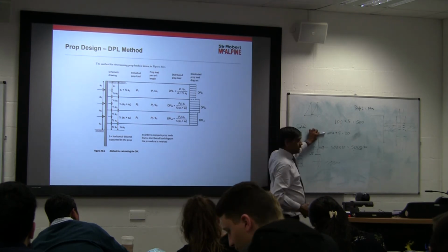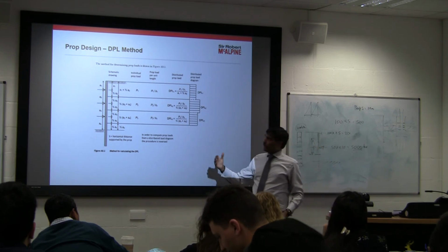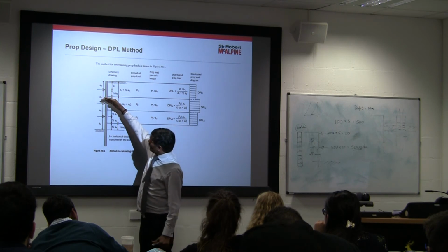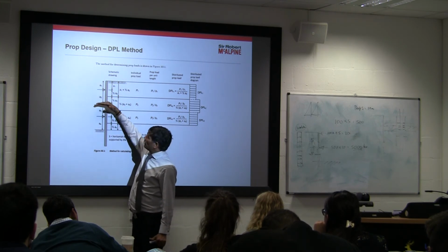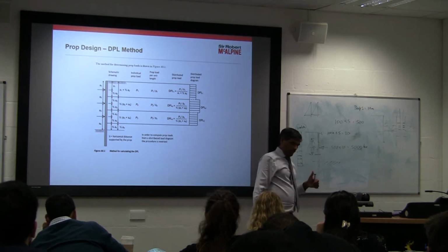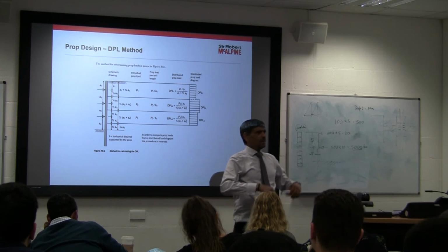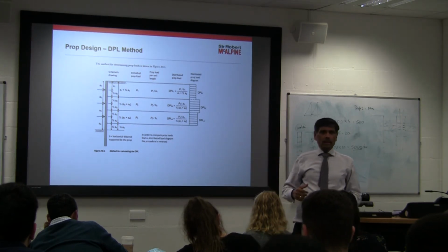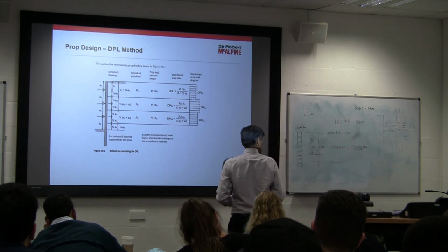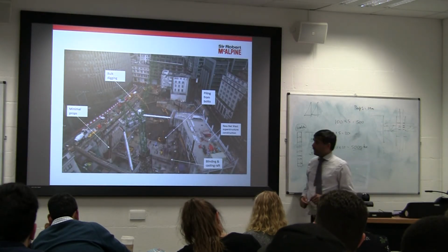Whereas if you put only one at the top, the forces will be half. Yeah? So if you are digging, let us say 20 meters, you have to think of multi-level props and then work out the load on those. Now, coming back to the idealized pressure distribution. So why do we use a sort of an idealized distribution? Why not a Rankine style? So I will come back to that.